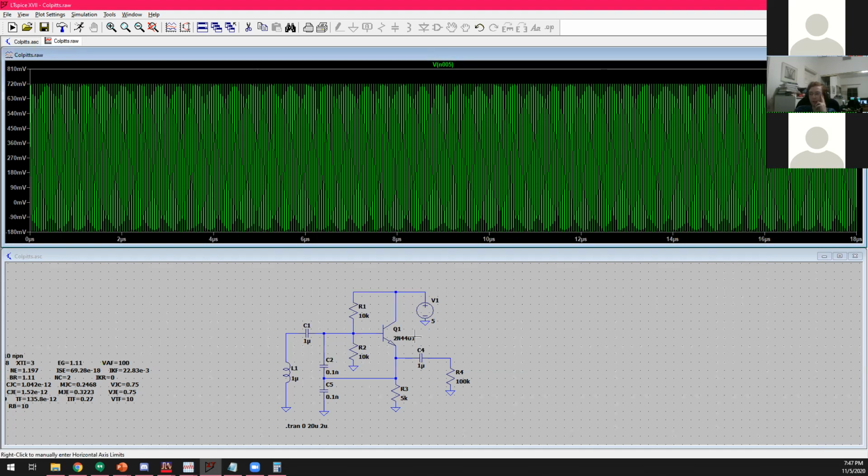But even below that maximum frequency, you get some non-ideal effects. Namely, you get capacitance between the base and emitter, and the base and collector. Specifically, the capacitance between base and emitter will add directly to C2 because it's in parallel. And so that'll shift your resonant frequency a little.